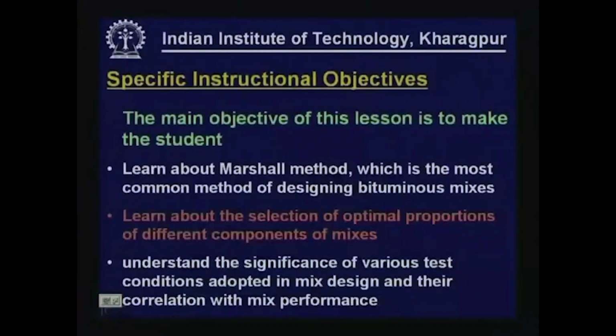and it is also expected that the student would be able to understand the significance of various test conditions adopted in the mix design procedure, because we are going to test bituminous mixes and then find out various parameters. So, these tests are going to be conducted under various conditions. So, what is the implication or significance of these different conditions, how they are correlated to the actual conditions, and what is the influence of these parameters on the performance of these mixes will be understood.